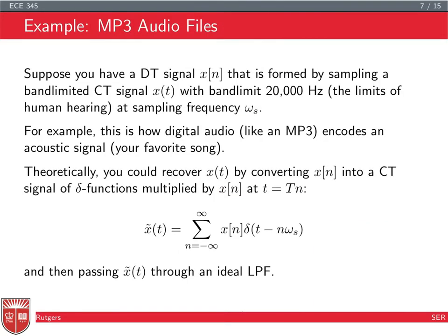band-limited signal. To give you an example, let's suppose we're talking about an audio signal. Typically human beings can hear up to 20,000 hertz, which means that all you have to do is sample an audio signal at twice that frequency. So you have to sample at 40,000 hertz. So fs, which I express in hertz, should be greater than 40,000 hertz.